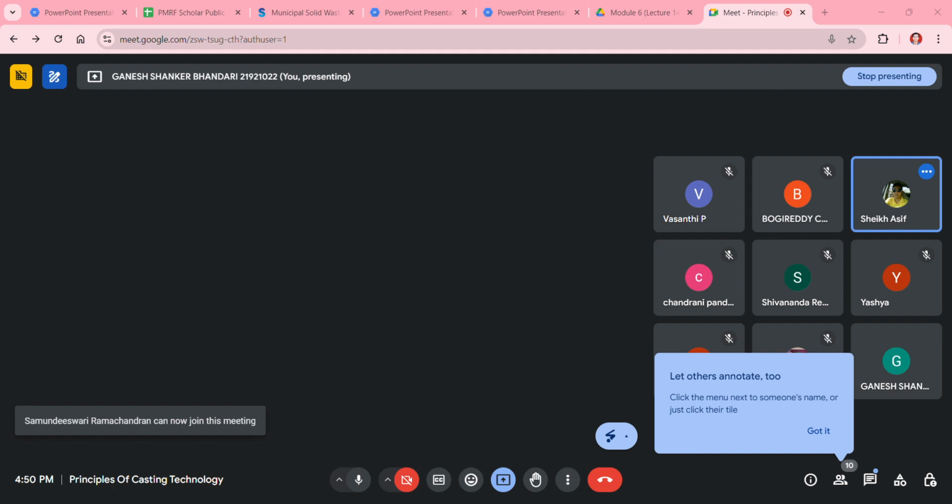We had talked about some formulations, TCS, total collection time. In that total collection time, we were not considering the on-site time. We are talking about the collection system, which will consist of your pickup time and haul time or off-route time, so your on-site time is not considered as a unit operation of a collection system.